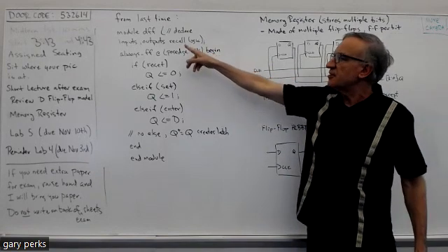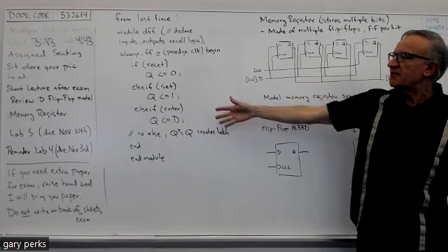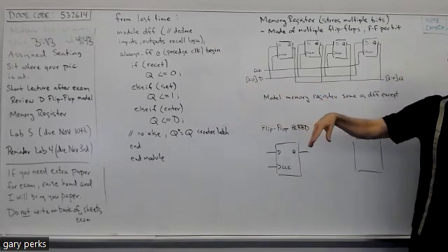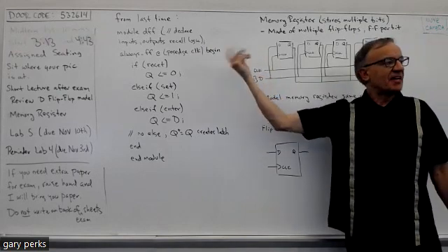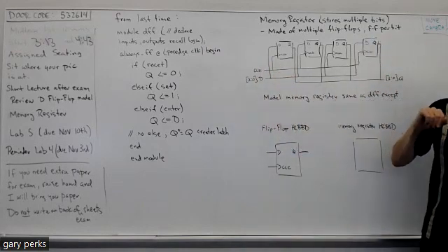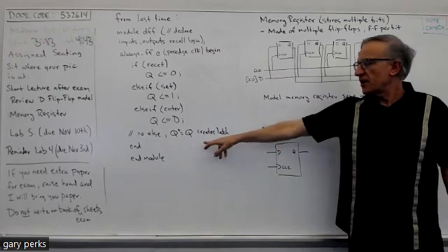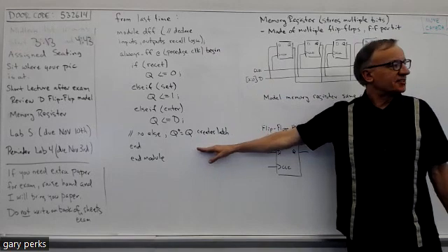You just have to declare your inputs and outputs. And again, remember that anytime you have an output within an always block, either always_ff or always_comb, you have to put logic where you define that output, so output logic and then the name of the output. Also recall that one way to create a latch is by having an if statement that doesn't have an else.